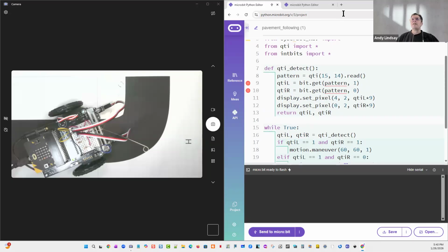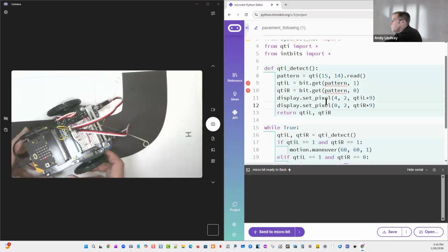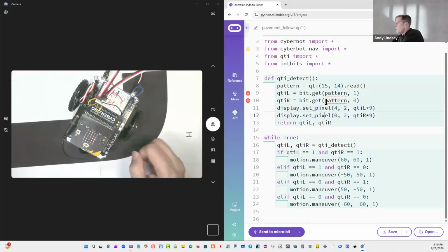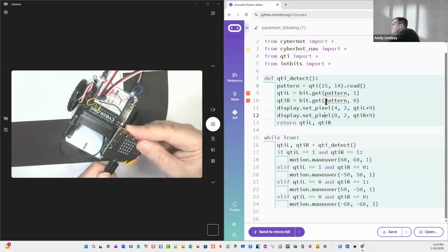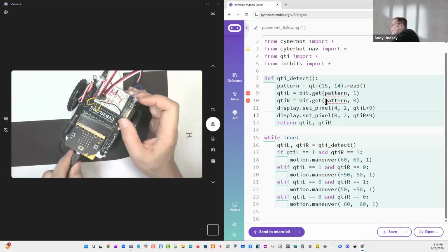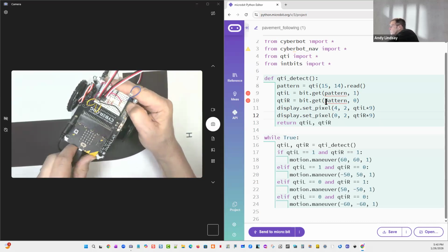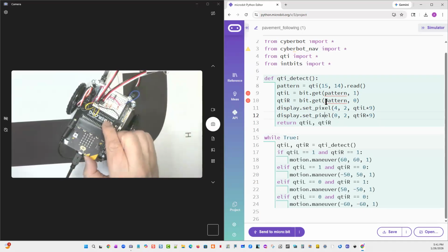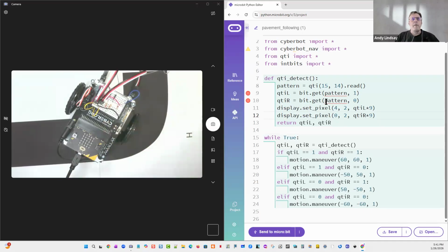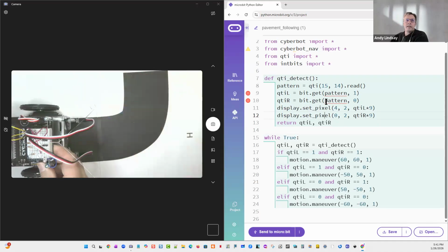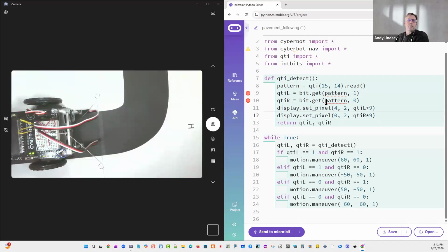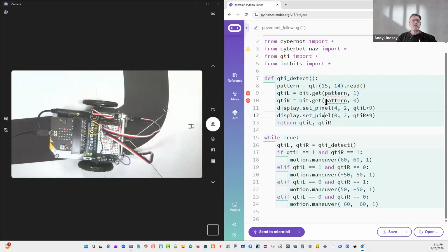So generally, if you close one tab and then, in a worst case scenario, unplug, turn power off, plug in the microbit, and then plug it back into the socket. I've had some students with laptops where, for whatever reason, that was the magic combination to get it to come back. And then you can try moving the switch to on and see if it cooperates.